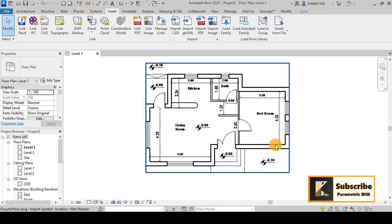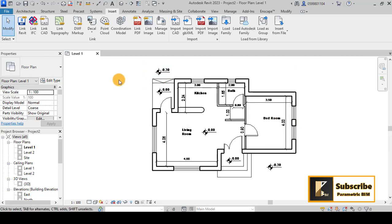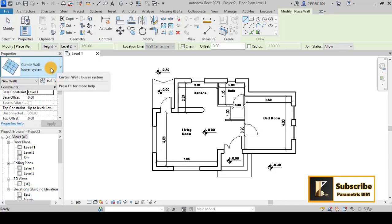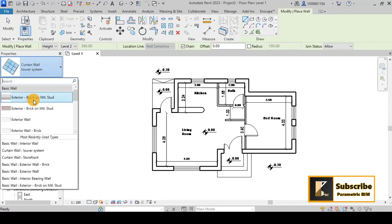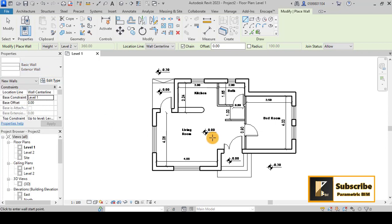So I am here in Revit with my imported plan. I will use these lines to retrace the work over them. First I will start with my walls and choose Wall, Architecture. Now you have the opportunity to choose what walls you have, but I will go with exterior wall, which is the generic that I have created in this template.